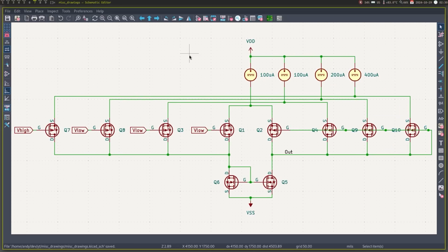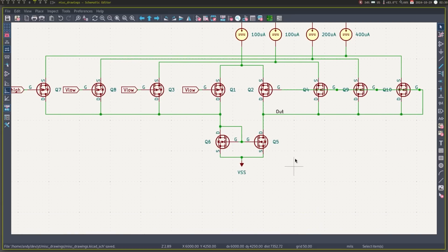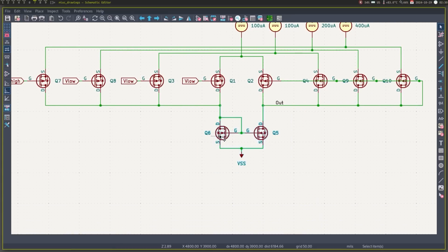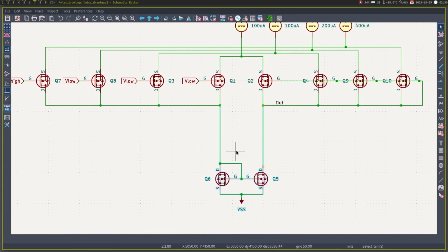Before we build up all of those differential pairs though, let's make a few improvements to the core op-amp first. The lower current mirror can easily be improved by giving it a cascode. This helps because changing the drain-source voltage on the FETs changes the drain current a bit, and the cascode keeps that voltage more constant. This now causes another problem, where we can't go nearly as low as the output voltage wants us to be.